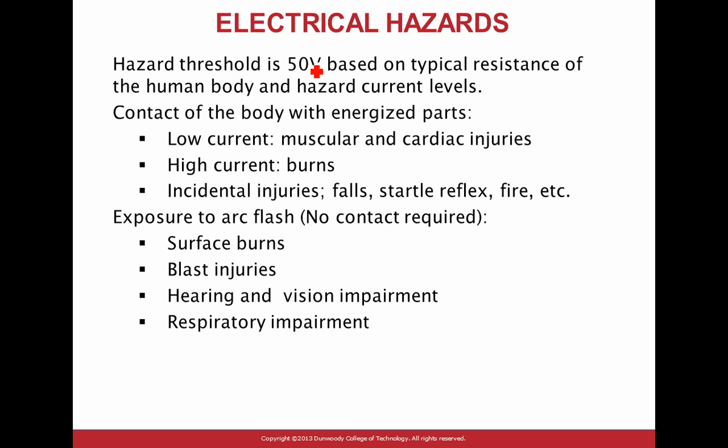The electrical hazard threshold is 50 volts, based on the resistance of the human body. If it's 50 or less, it's considered safe from a human point of view, but not from an explosion point of view. You could have 50 volts, guys, if you're using hazardous material. A little arc coming out of a 24 volt or 12 volt battery can ignite the whole building if you have flammable material in your area.